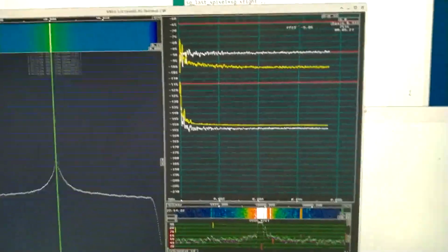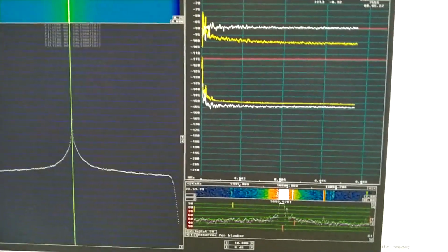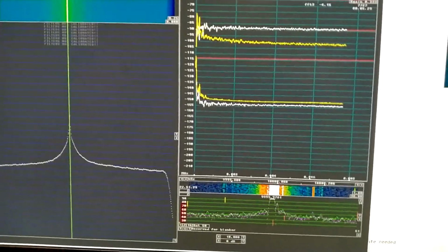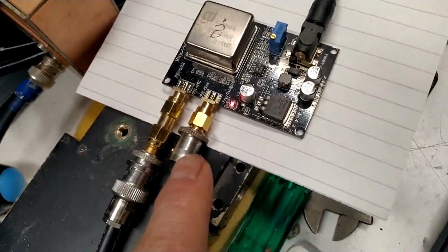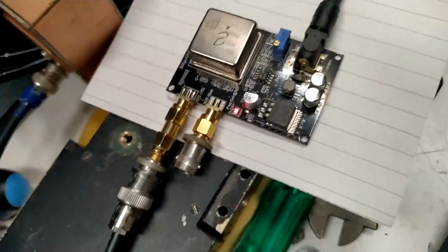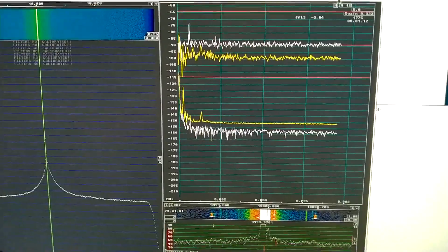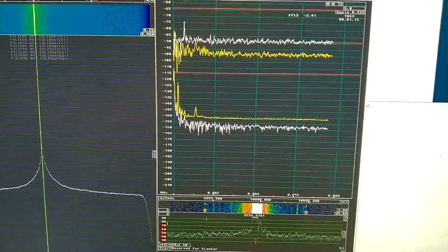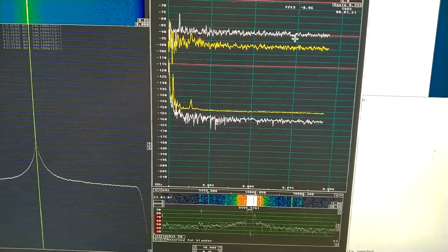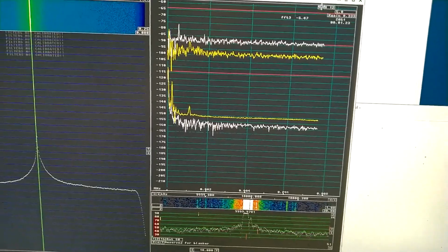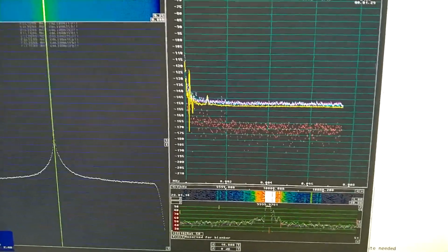And here is what I see. The amplitude noise is much weaker. And the phase noise is also a little bit weaker. There are two outputs on the unit, one here for sine waves and the other for TTL. I will put a short on the sine wave output here. This seems to improve a little bit more, but the amplitude noise is very noisy, and therefore the correlation curves also become noisy. If I click here to look at the phase noise, it looks very good.